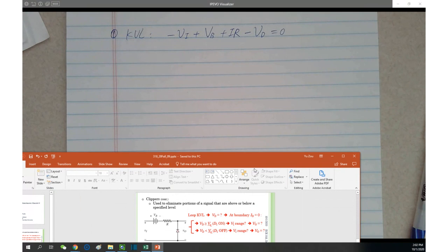Well, that's actually exactly not the mistake I made. Be very careful, everybody. When you define a VD, you're defining the anode as positive, cathode as negative. In that way, you can say VD is greater or equal than V gamma or less than V gamma to decide on or off, right? Because if you reverse the polarity when you define it, then the result can be completely different.